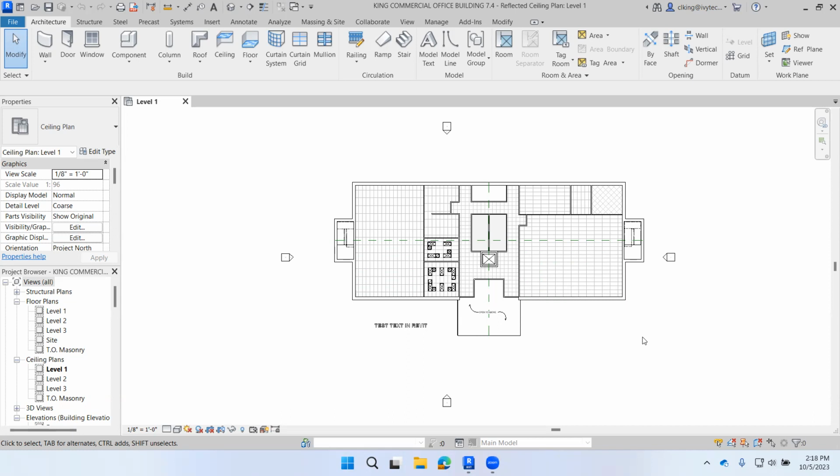Here you will look at setting up an exterior elevation and how to control some of the various options. Setting up an exterior elevation, even though you already have the main exterior elevation set, you will go through the steps necessary to set one up. Many projects have more than 4 exterior elevations, so all exterior surfaces are elevated.